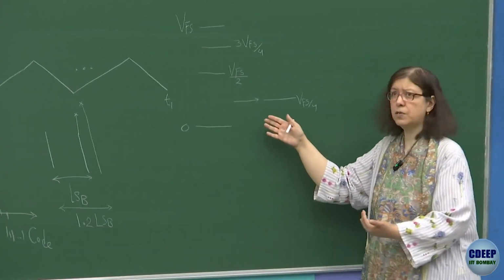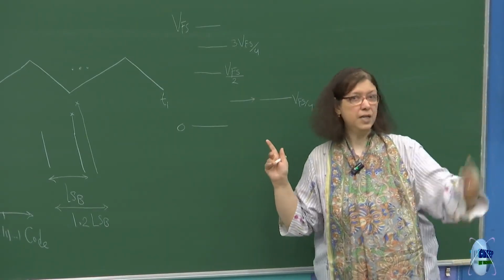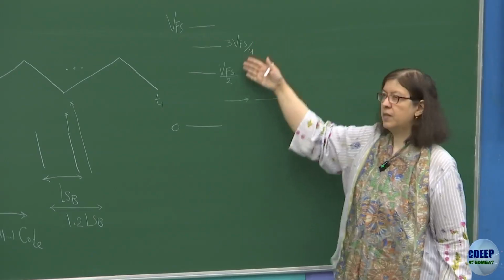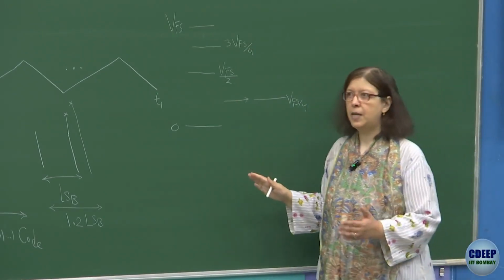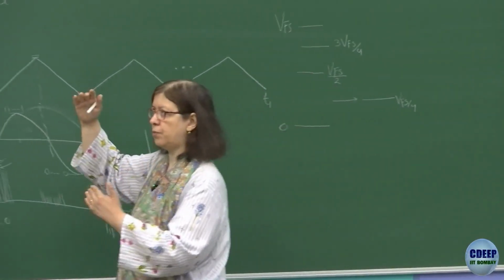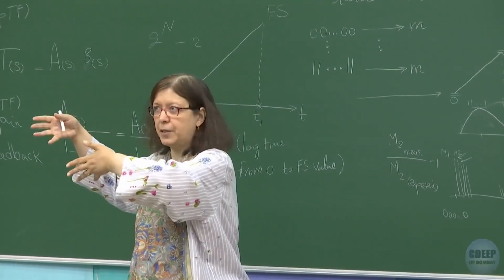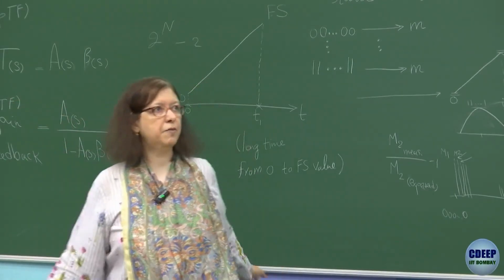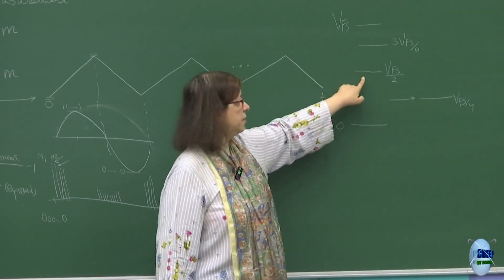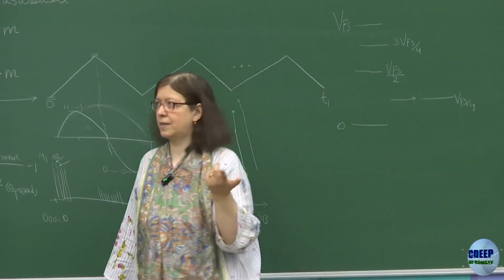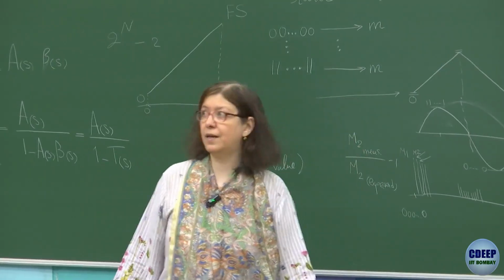Of course, it could also start from the shifted version. You know that LSB upon 2 shift. Therefore, still it is a binary search, but you can shift all these values by LSB upon 2 down. So method will remain same. Eventually, it tries to divide the range into 2, upper half, lower half. Depending on that, again the next half will be divided by 2, and this will continue till number of bits are generated. So therefore, every search and generation of the reference value becomes at least 1 clock cycle. Therefore, for n bit, you need at least n clock cycles.